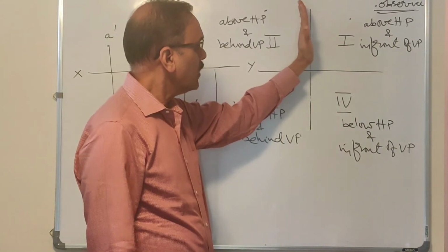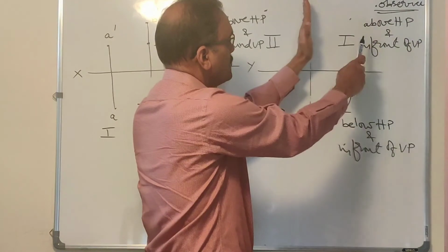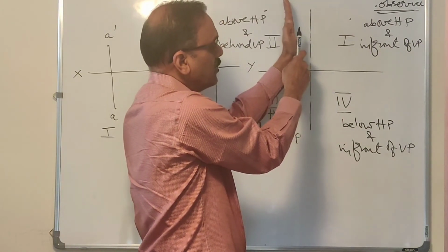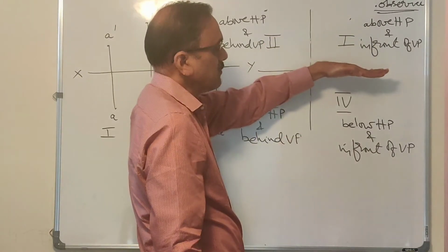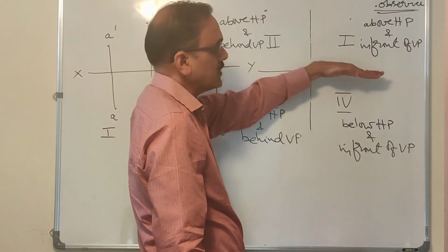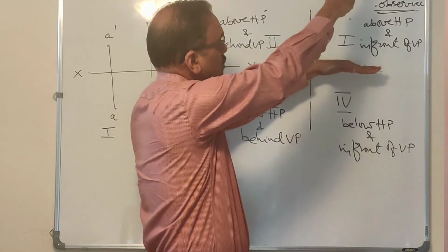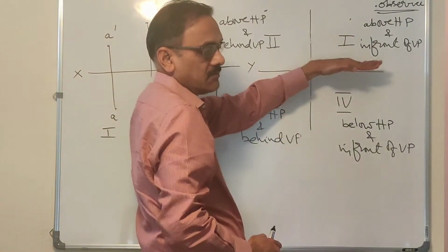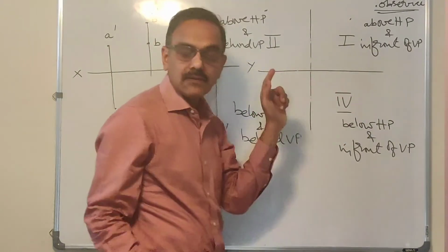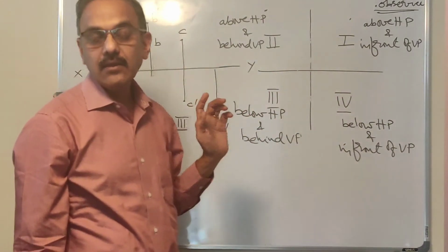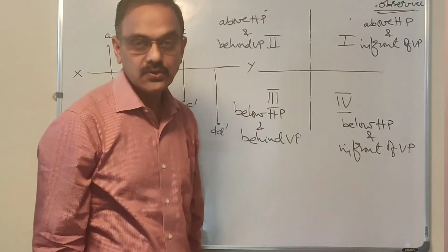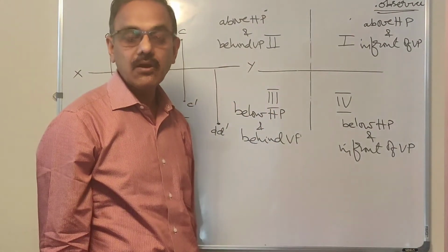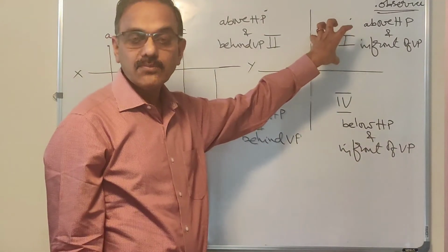So when you get the front view, observer, object and plane of projection, that is the order. Similarly, when you get the top view, this is the horizontal plane you have to consider. Observer is there on the top, the object is there in the first quadrant, and this is the plane of projection. So that order is defined clearly both for the top and front views. Observer, object and plane of projection is the order when you have an object in the first quadrant.